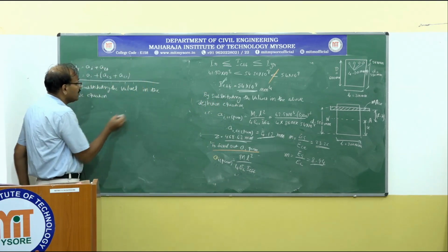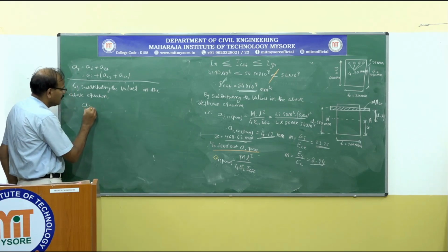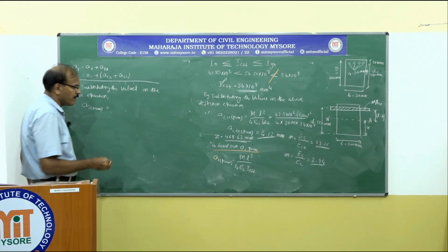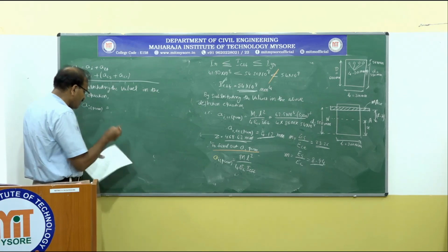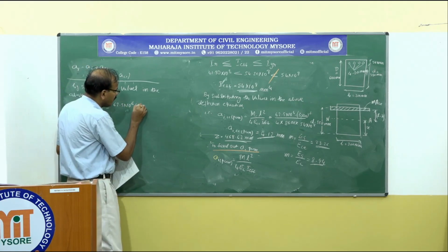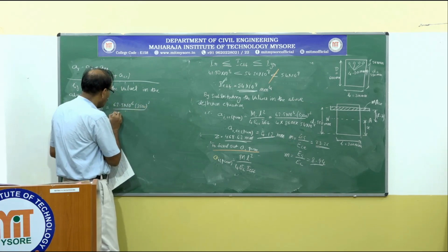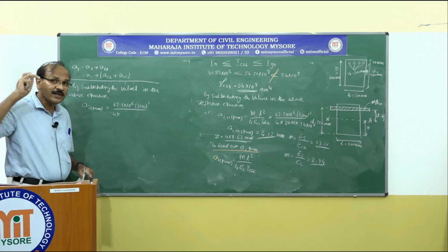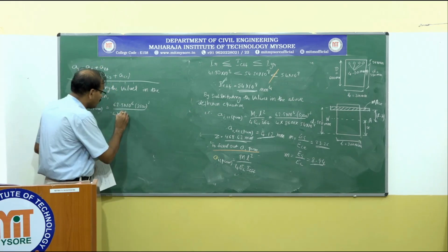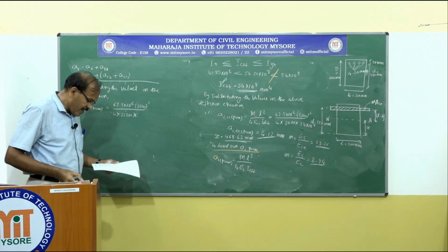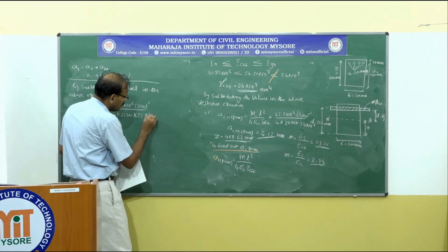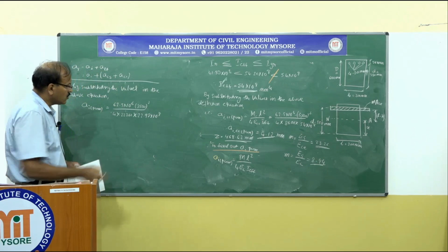Okay, above equation, AI permanent, that is the immediate deflection due to permanent load, equal to M, which is 62.5 into 10 to the power of 6 Newton millimeter, L is 3500 square, 4 into EC, it is not ECE, instead again I am repeating EC, that is equal to 5000 root of FCK, that is equal to 22,361, and I effective 22.97 into 10 to the power of 8. So, we have done calculation for this.